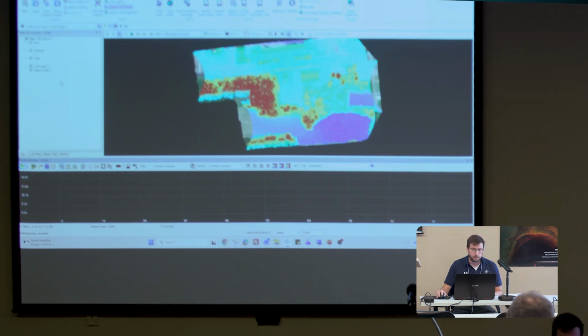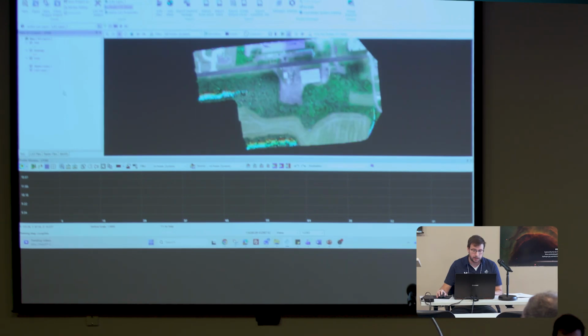Notice how I really didn't cover this the last couple of days, but if you use LP360, we're looking down in the table of contents at the different layers. The top layers are like looking down on a sandwich, and as we peel back the layers, there are different layers of that sandwich. So you can left click and hold any layer, and you can adjust its position in that sandwich, so to speak. So I'm going to move the raster layer on top of the LAS.